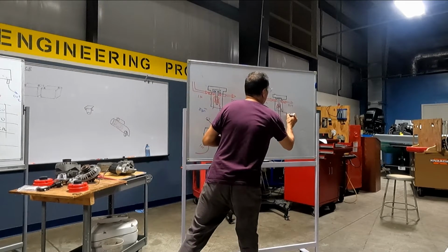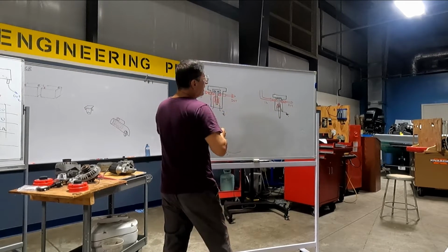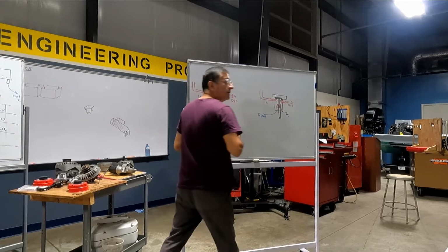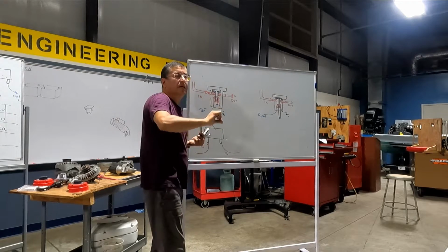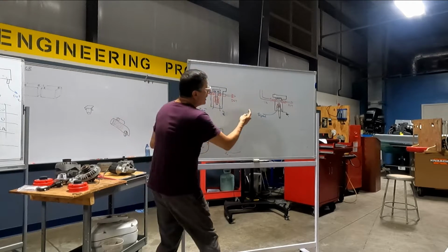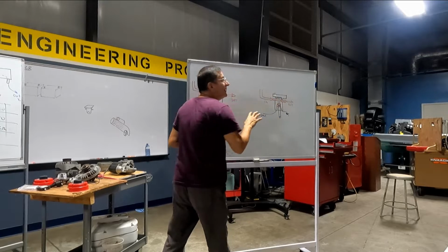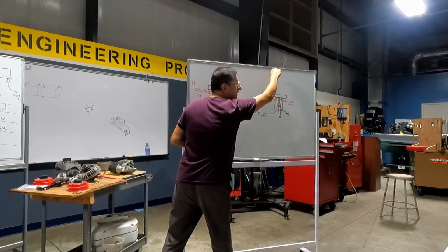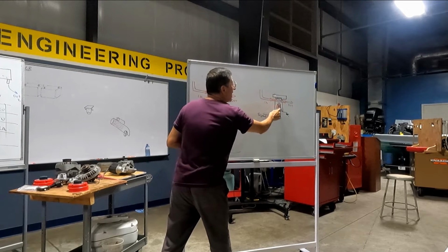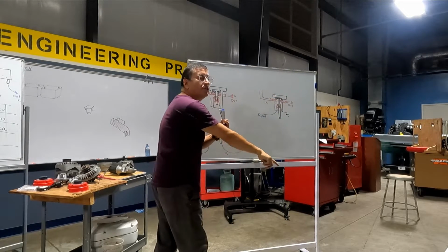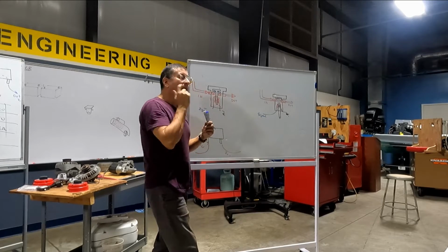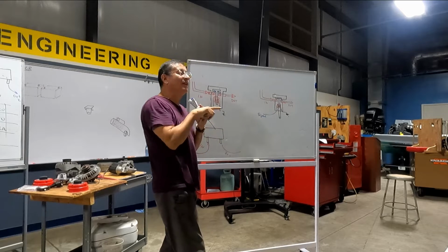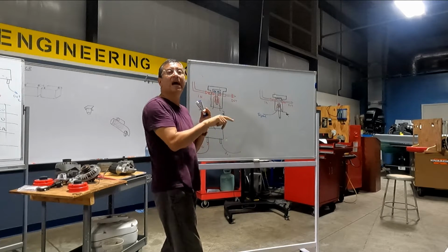One terminal is a ground, and the other terminal is the signal, from the ignition switch or the toggle switch, any signal. When I bring the signal, what happens with this solenoid? What happens with the gap in between this and this? Closed. But additionally, the metal extends outside. I hear the click, the current passes from this point to this point, and additionally, the metal goes out.